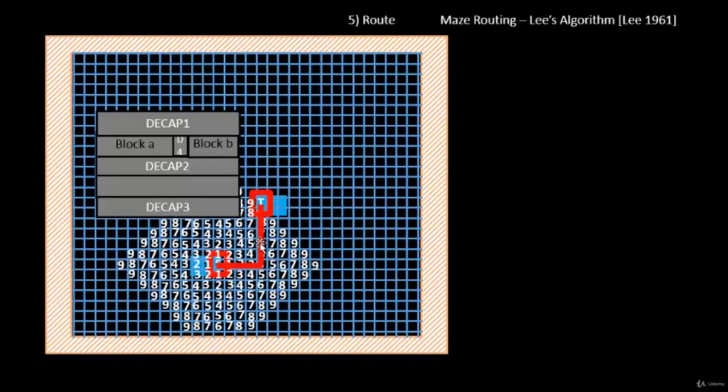Okay, so this is one of the routes that this block takes to this particular block, and this maze algorithm is being used for global routing. There are some limitations to this. For example, if you see, it creates a maze first, then it starts numbering from source, then it moves to target. So for one route was fairly simple, but if we have like millions of routes, this method tends to consume lot amount of time and memory. Okay, because it has to store all the information. Whichever is the best route, it has to store all the information.